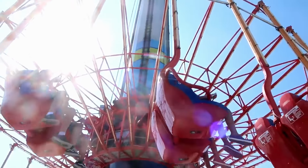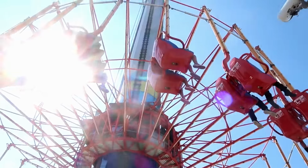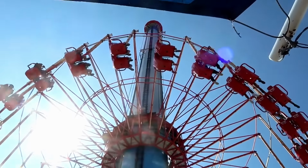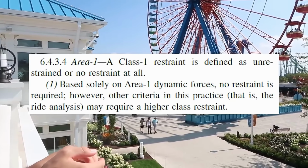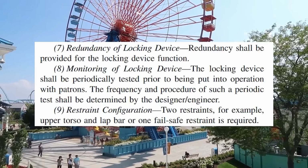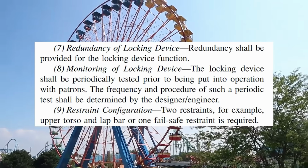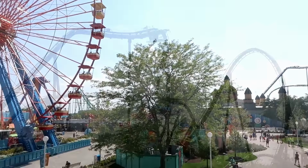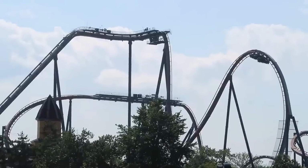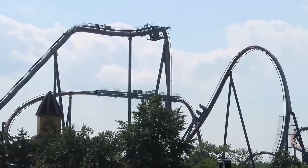ASTM breaks rides into 5 categories, with corresponding restraint design requirements depending on the predicted forces the ride will subject riders to. These categories range from no restraints for rides that have very little changes in acceleration, to redundant restraints that secure the rider in multiple ways when rides experience strong negative Gs. Restraints are broken into 5 different areas by ASTM based on the G-forces riders will experience on the ride.